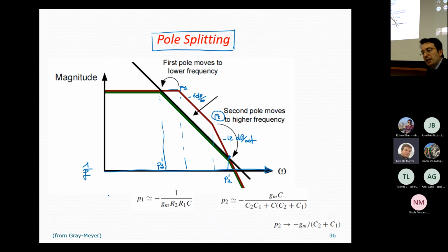If we do so, what we can do is move this 45 degrees to the right-hand term and all this term to the left, or multiply everything by -1 to get this result. 135 degrees, that is 180 degrees minus 45 degrees, should be equal to the arctangent of omega null over the modulus of P1 plus the arctangent of omega null over the modulus of P2 plus the arctangent of omega null over Z.